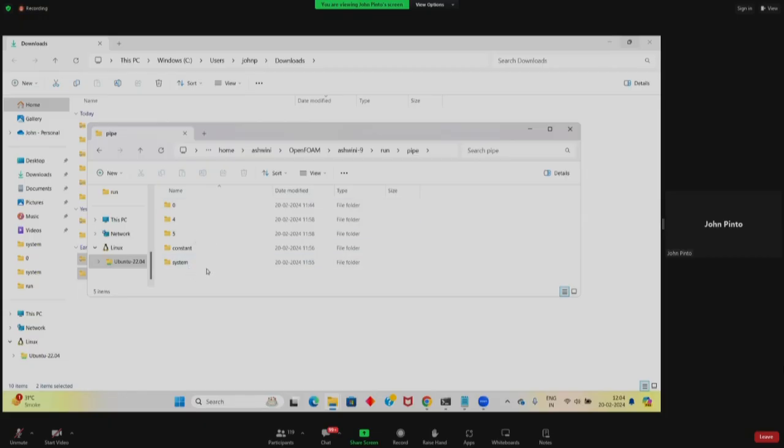But when you do the mesh and you want to visualize the mesh using paraFoam, ParaView by default opens the 0 folder to check what the values are, and it loads those values. Now what it will see is that in the 0 folder you have defined, say, one patch called moving wall, which was there in the cavity, but that moving wall is not there in your blockMesh because you have already changed it, and you have not changed the 0 folder. You haven't changed it because right now you are not interested in that. You are only interested in the mesh at the moment.